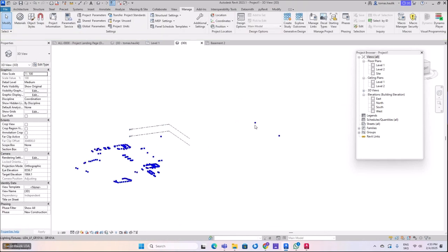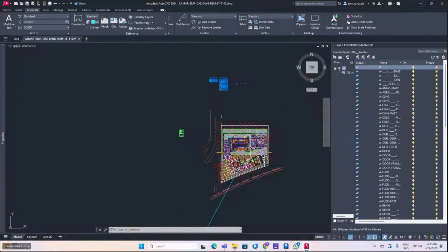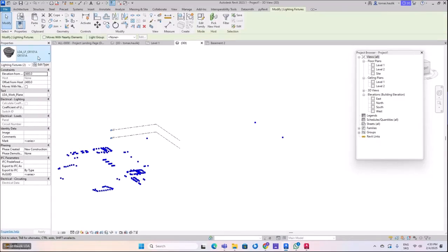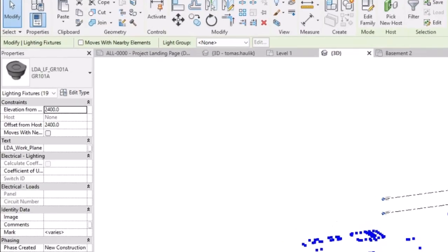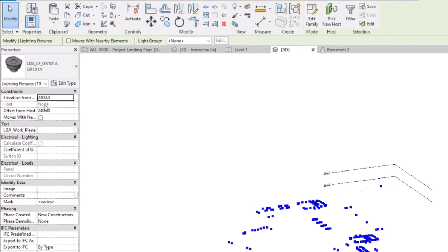And actually, what I did is I used the DWG as we usually use. So as a result of that, we have these 2 elements flying out of nowhere because in the DWG, they were used for the legend. So I'll just delete those. Now, I will see that host is none. That's not quite correct, but we can actually do something about it in the file where we're going to carry over.